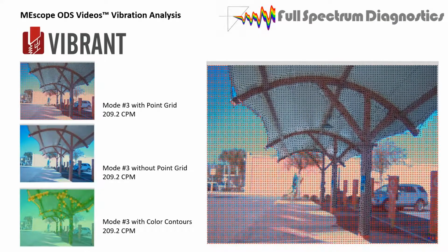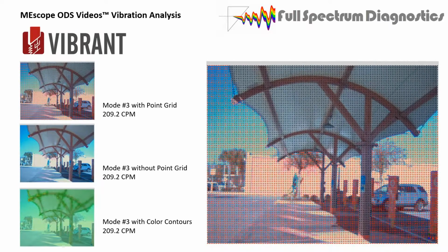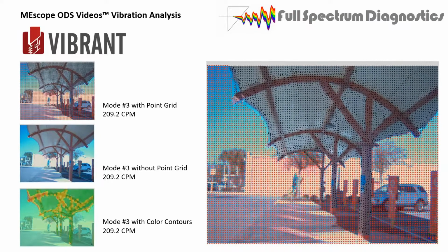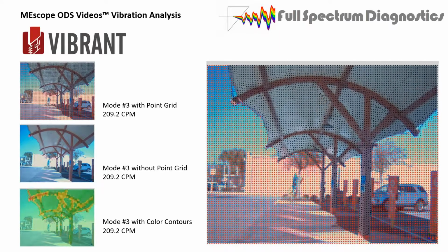And you're going to have so many different modes from this because there are 4 different truss structures, and they're pinned together with each one of them. So you're going to get multiple modes for each and then together, and it gets a little overwhelming. And like I mentioned before, if I was doing an analysis like this, it would be a lot easier just to use MEscope to make a finite element model because all the physical structures are pretty simple, and get it all pinned together and what have you. And I have those rigid body modes, so it should tell me where all the other modes would be, and they'd be pretty accurate.